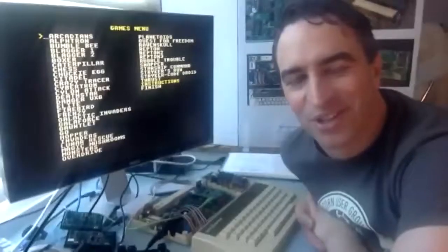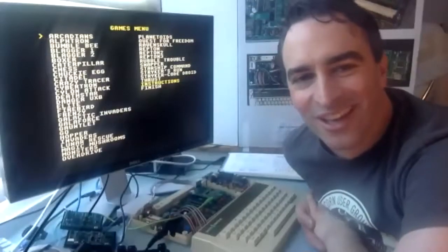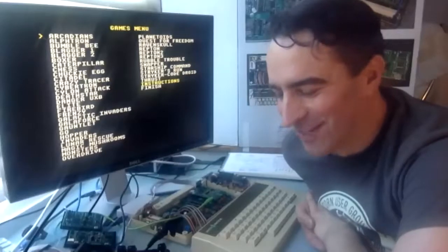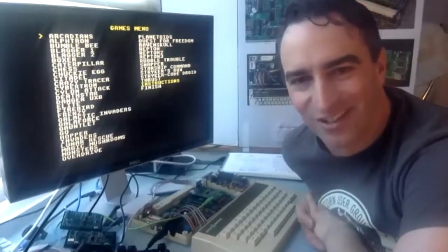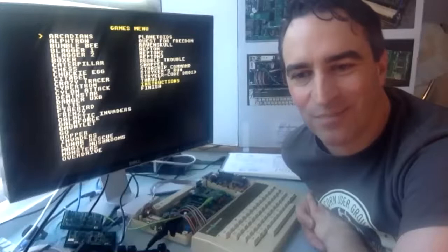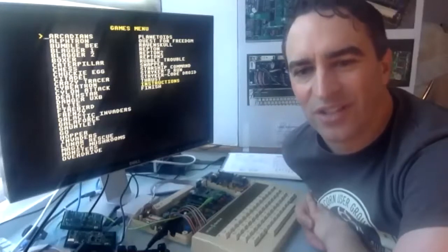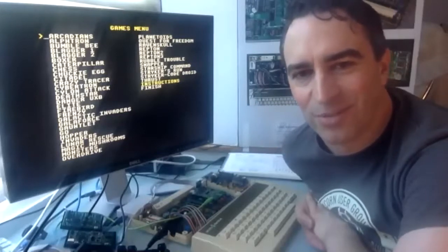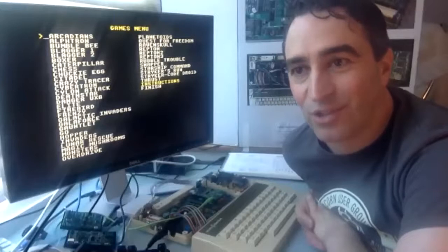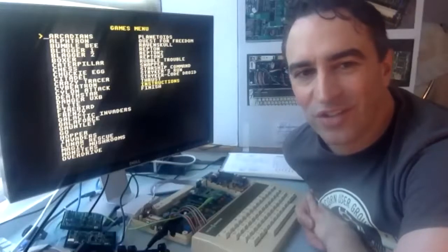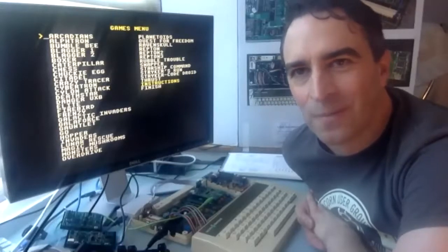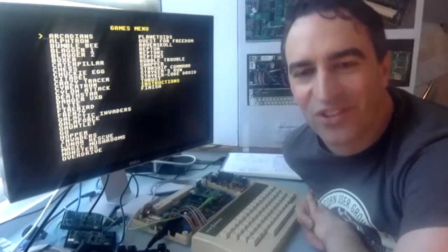Oh, all right then. This isn't as terrible as I thought. And then we'll be able to have some really nice tests. Test the whole system with, I'm pretty sure I found a Verilog test version of the SDRAM chip, which is ridiculous. It's so funny seeing SDRAM implemented using that sort of test-only, non-synthesizable Verilog.